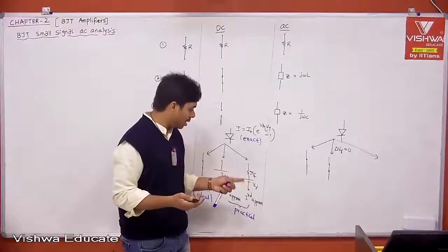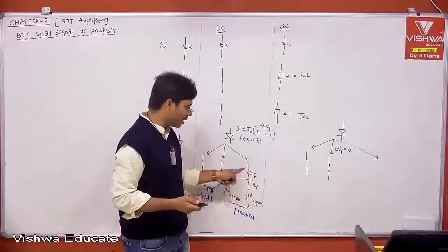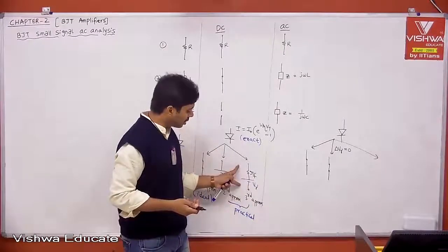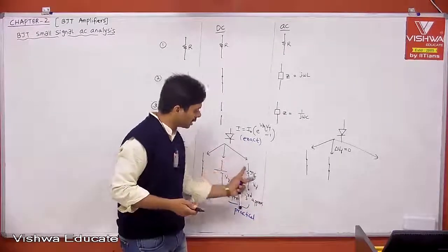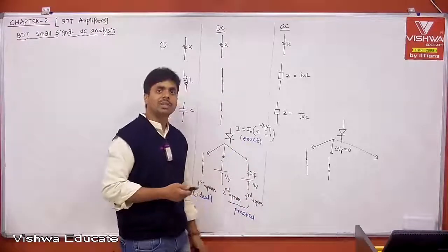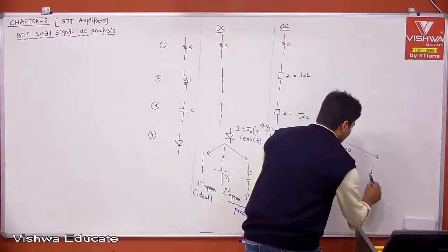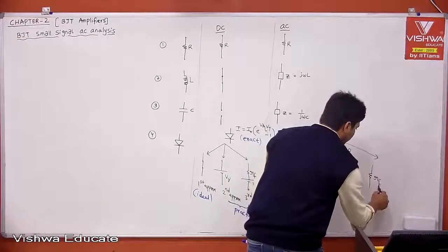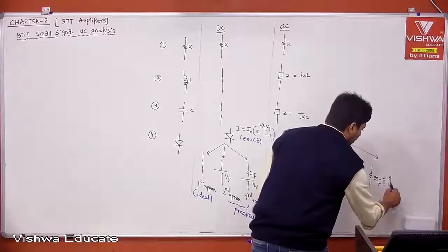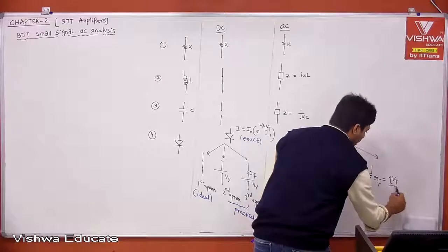That is not there, but this R_f is the one which is already described. The change in voltage across the PN junction, the change in the current, is described by your small r_f, which is already represented in the third approximation. That will be there as it is. Therefore, it is simply small r_f. What is the small r_f? Eta V_T divided by I, which you already derived.